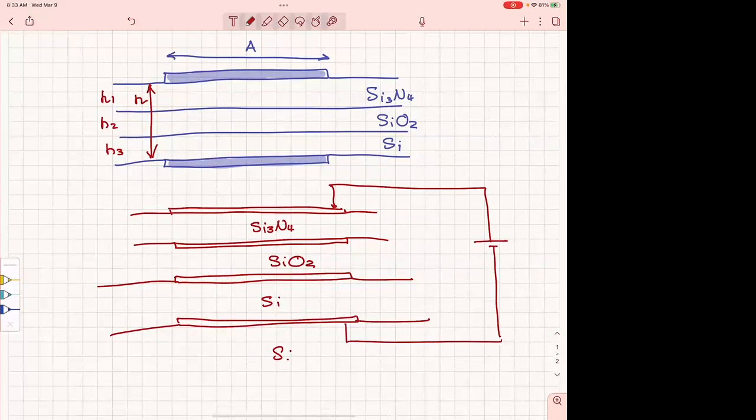Let's assume that you put here a voltage source, so you excite it. You remember the problem we did? Let's assume that these are not connected to anything. This is equivalent to three capacitors in series. That's what we have seen through the exercises as well. We had even more crazy metals, but if the intermediate metals are not connected to anything, these are three capacitors in series, even if there are no metals in between.